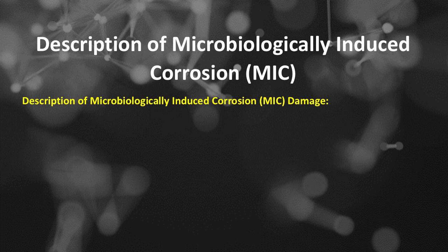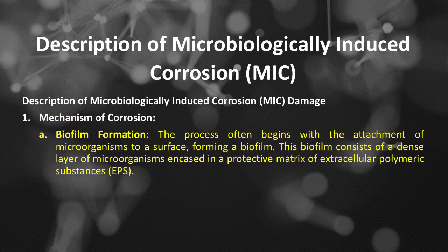Description of microbiologically induced corrosion, or MIC, damage. Number 1 is mechanism of corrosion. Number A, of mechanism of corrosion is biofilm formation. The process often begins with the attachment of microorganisms to a surface, forming a biofilm. This biofilm consists of a dense layer of microorganisms encased in a protective matrix of extracellular polymeric substances, or EPS.